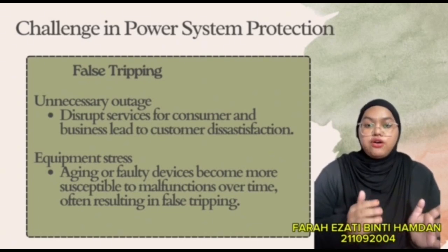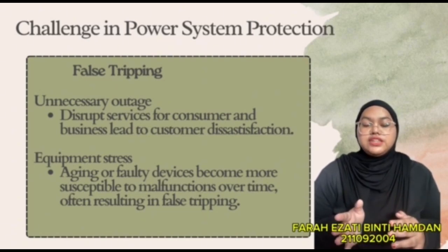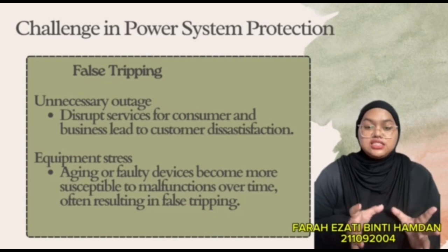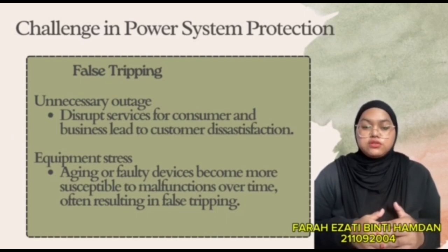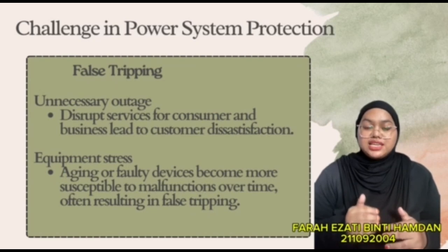And aging or faulty devices become more susceptible to malfunction over time, often resulting in false readings. Additionally, in systems that depend on communication for protection coordination, any failure or latency in communication can lead to false trip.